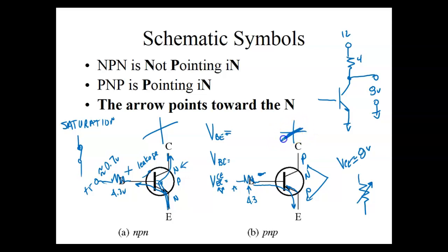I drew it. So what we're going to do is forward bias the base to emitter, and reverse bias the base to collector. And the collector voltage is going to be a lot higher than the base voltage, right? In fact, once it starts working, the base voltage is going to be around 0.7 of a volt.